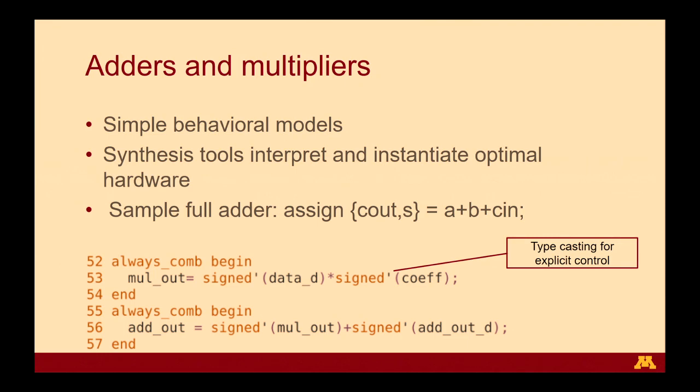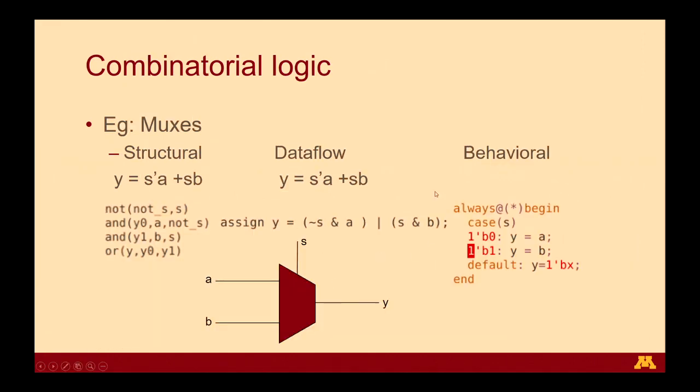In general, when you have memory within a block, the synthesis tool detects memory based on whether there's any condition which cannot be uniquely determined by the inputs. For example, if in this always block only one of these conditions were filled, the second condition was not filled, and there was no default statement, the synthesis tool will interpret this as a memory, because if, for example, S is equal to 1, it will just hold the previous state.